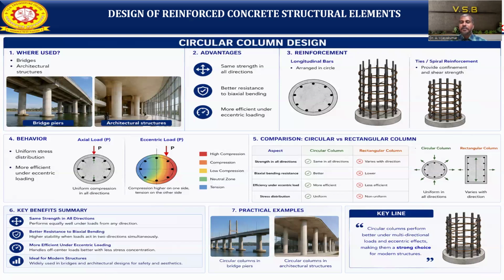So it will be the reinforcement detail. We use circular longitudinal bars, and here you can use spiral reinforcement, which provides confinement and shear strength to the column. For behavior, there is uniform stress distribution along the entire cross section of the column, more efficient under eccentric loadings.